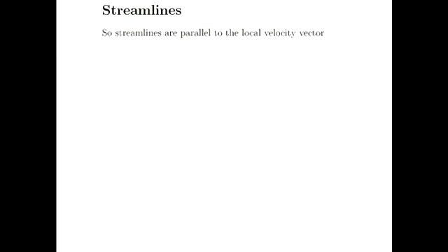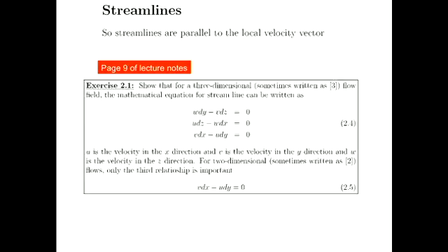So streamlines are useful for us as engineers, okay, and they're parallel to the local velocity vector. I guess that kind of wall tufting would be, for those of you involved in that motorsports capstone project, a pretty useful way to go rather than going straight for the CFD or straight for the wind tunnel experiment. If you want to know what the flow's doing into your cooling boxes where the radiator is, or over your front and back wing, that's a kind of $2 attempt at having a first look at that flow.